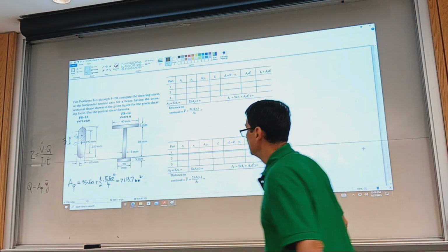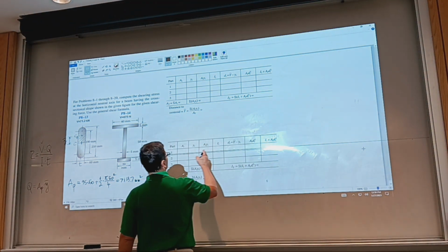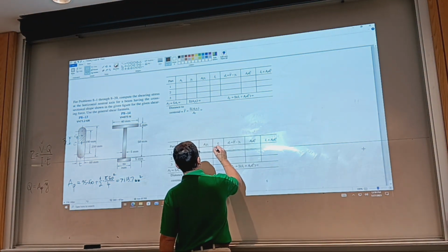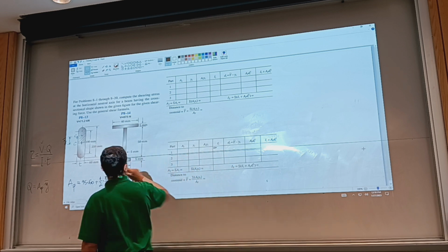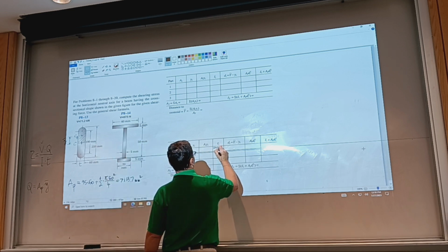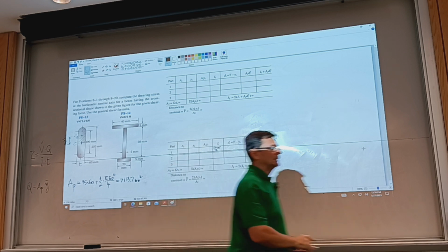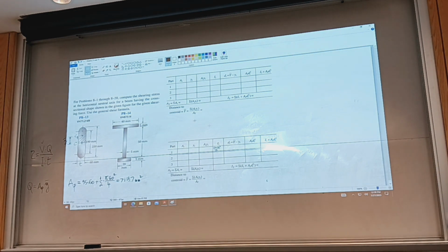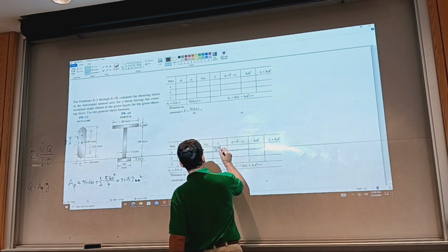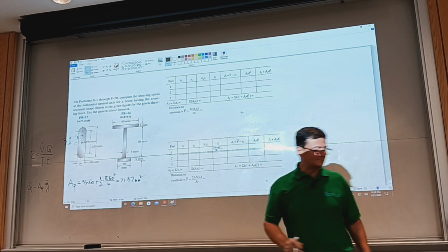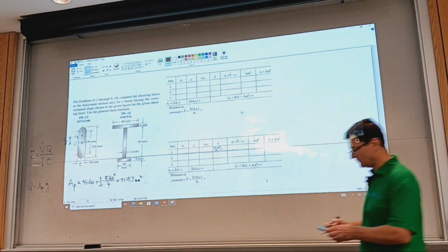So B, that is 60, and H is going to be 190, over 12. Okay. Any more space? So I can stretch this, or do whatever. All right, so what is this value equal to? This is the rectangle. And then we have half discs. Two of them will have the same area moment of inertia.